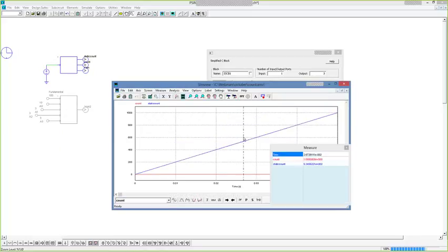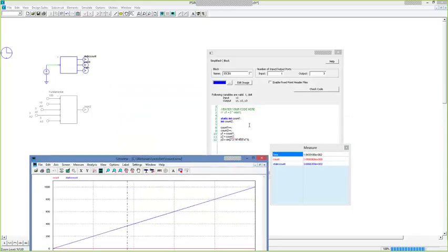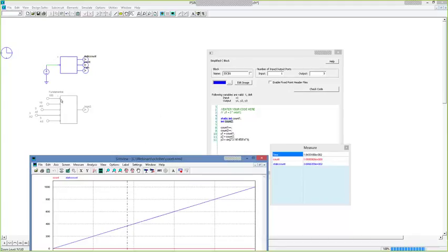Let's look at what happens. So we can see that one count just stays 1 all the time, while the other one actually increments. So the static count is actually counting how many simulation steps we went through, because this is executing at every simulation step. What that says is the regular integer is being released every single simulation step, whereas the static int was declared once, and then you can remember it all the way through. So that's a good point to highlight.